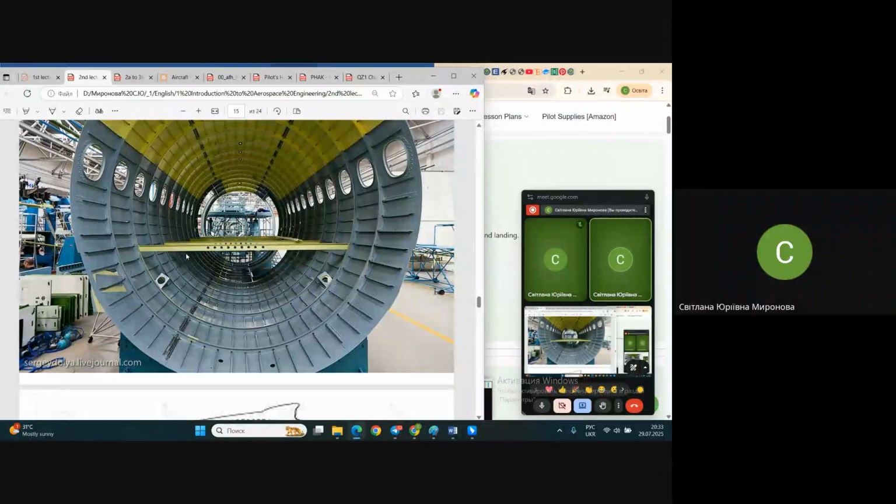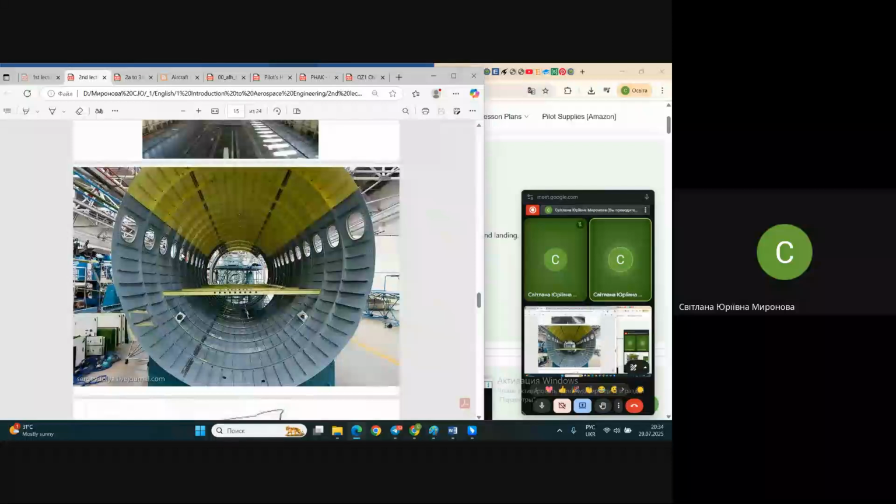They are thin. So what is called semi-monocoque consists of transversal elements, frames usually, and these stringers, but there are no longerons in the fuselage. All the stringers are practically of the same size, of the same cross-section. That is a structure which is called semi-monocoque.